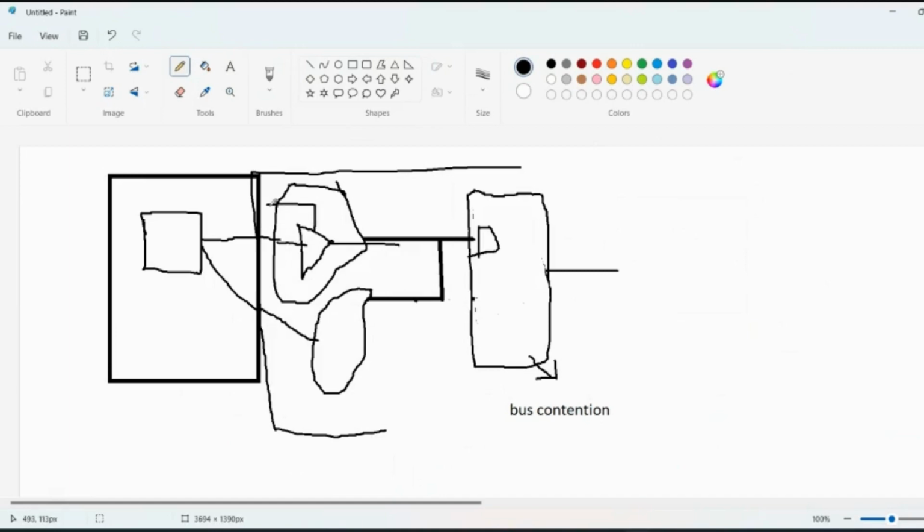and you have an enable signal, you also have the same here. So this is a controlling element. I mean, this buffer has a control element which has to be enabled again. Same here. If it has a tri-state buffer, okay, and it has a control signal, when you enable that control of the buffer, then only the value can pass through. So if you have this tri-state buffer issue, then this is a tri-state buffer contention issue.